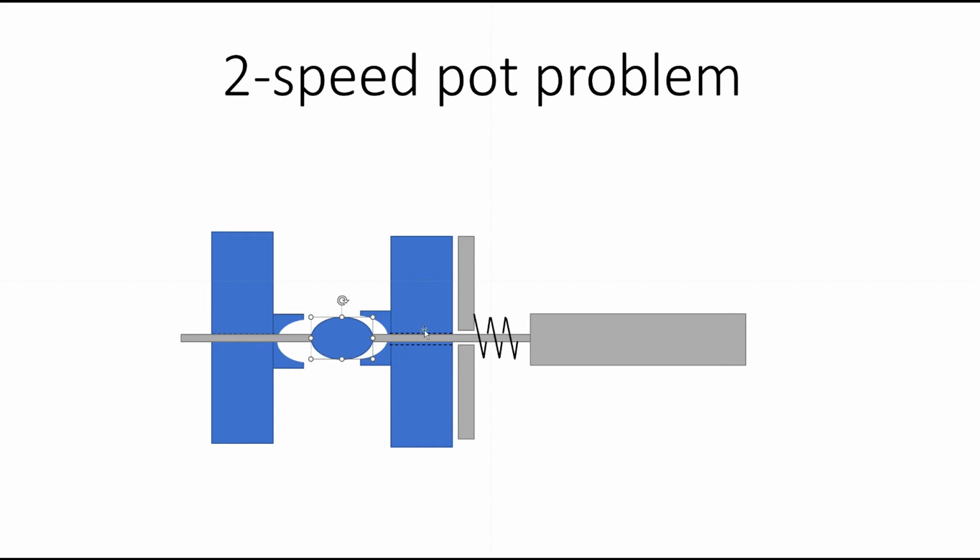Now what's supposed to happen is that this end here is where the knob goes. When the knob is released, the spring pushes out, and this little bead here snuggles into the little cup that matches on the front pot. And these are both textured. They've got little grooves cut into them, so they will lock together reasonably well under the spring tension. And then when of course you turn that knob, the bead turns because it's attached to the shaft, and the pot turns because it's got a good friction fit with the bead.